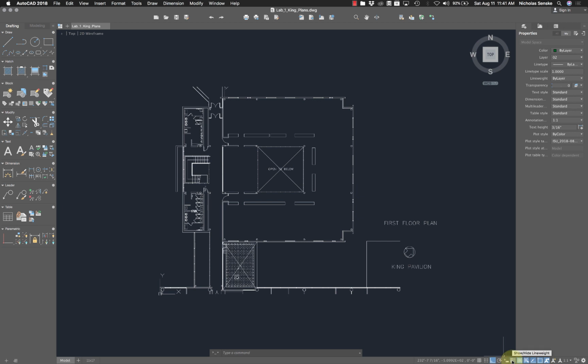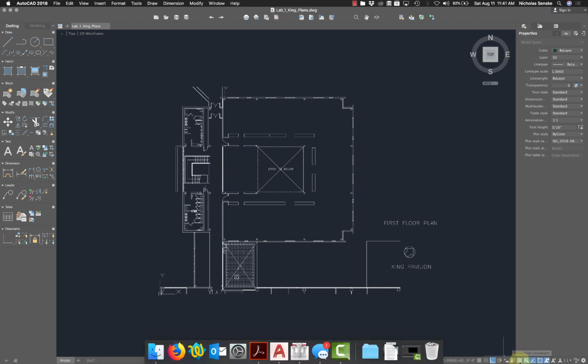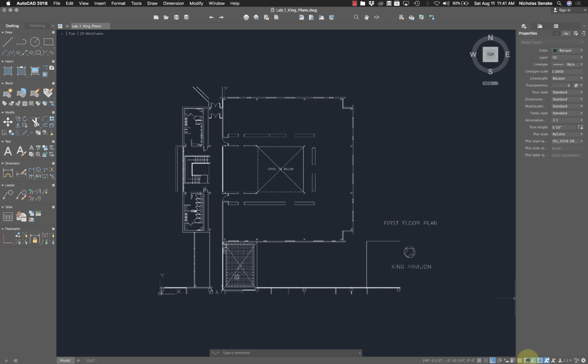Turn off the line weights. They don't really work that well anyway. We're going to go ahead and turn off transparency. Let's see here. I got glitchy. Nope, no group selection. Annotations, nope. Polar angles or object snap tracking, no.